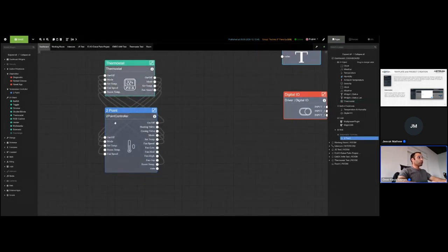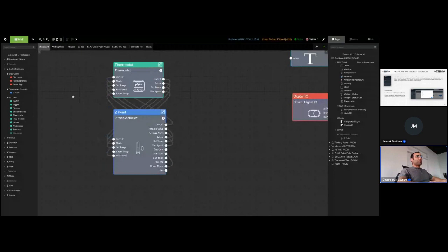Here is our controller. This controller is inside the panel. So the panel will be able to control this heating, cooling system. Because in this scenario, the controller is the panel. So this is controller, this is our UI. And also we need to add a relay module because we need 4 fan relays and we need 2 valve relays. Okay, let's go to device page.